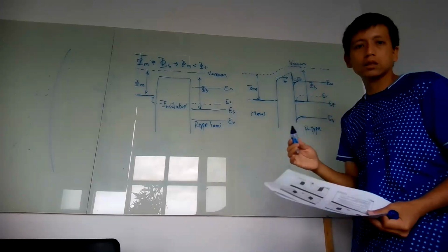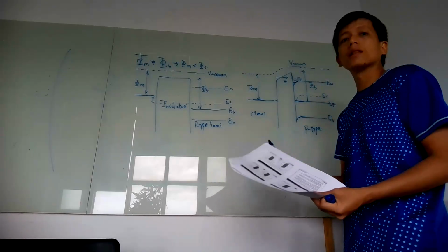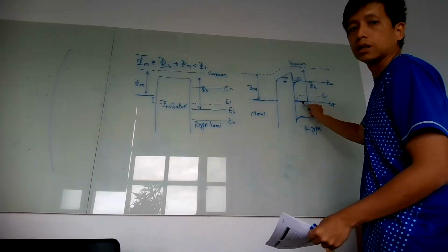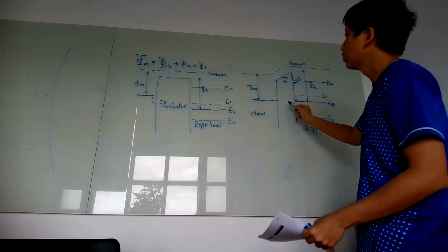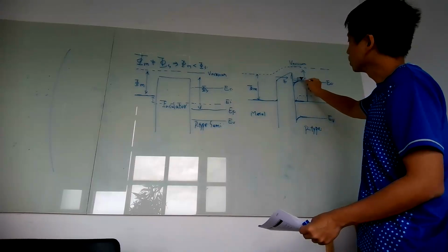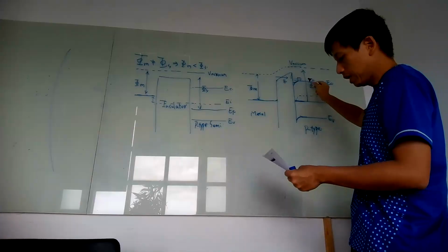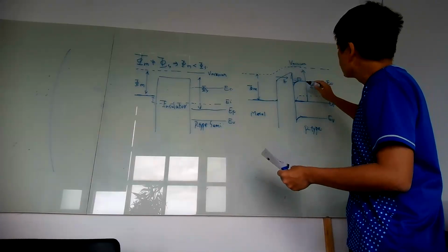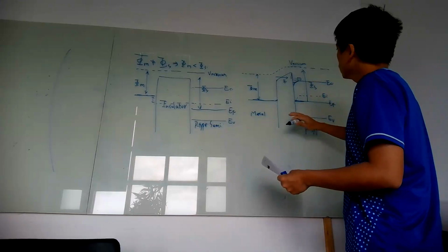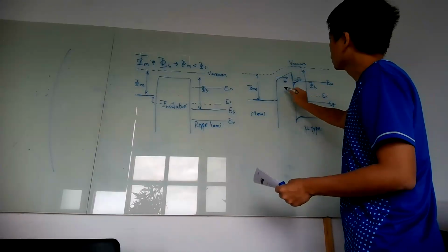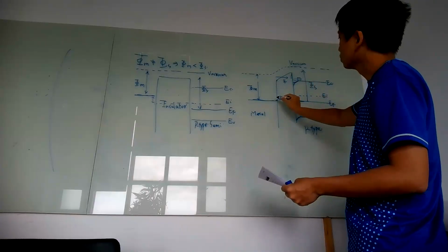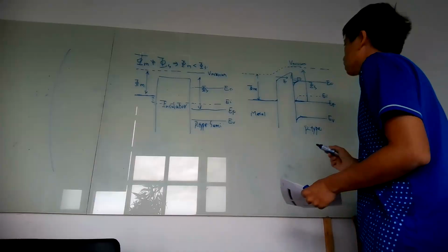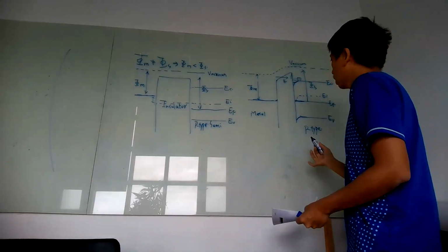Since the electron in the p-type region is a minority carrier, you can consider the minority carrier will first accumulate to cancel out the majority carrier. So in the p-type region, the majority carrier is the hole carrier. We get a cancellation or depletion in between these regions. For this one, you can think that the band structure will accumulate like this. As we previously mentioned, we get a negative charge and a positive charge, so we get an electric field from left to right.